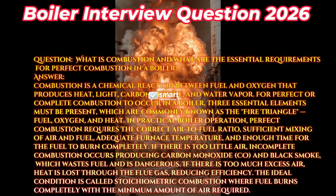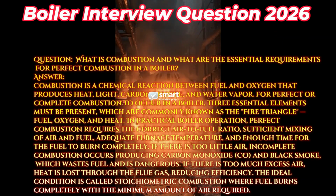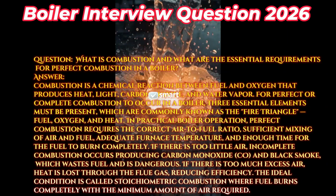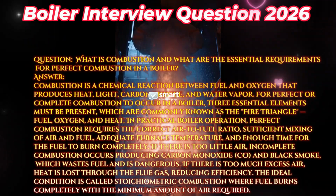For perfect or complete combustion to occur in a boiler, 3 essential elements must be present, which are commonly known as the fire triangle: fuel, oxygen, and heat. In practical boiler operation, perfect combustion requires the correct air-to-fuel ratio, sufficient mixing of air and fuel, adequate furnace temperature, and enough time for the fuel to burn completely.